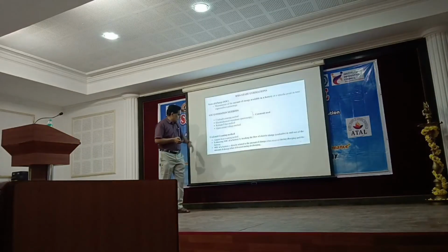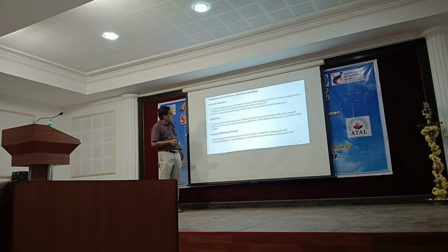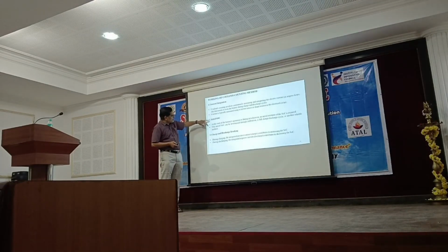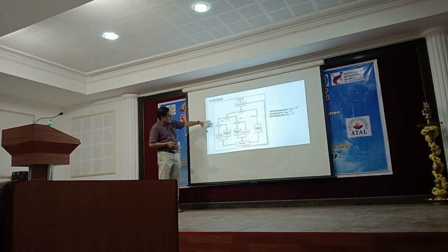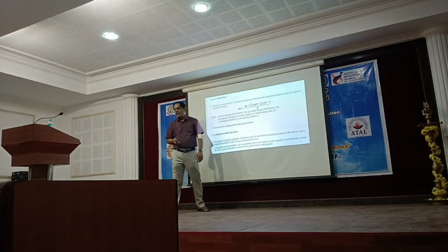And again, we have optional voltage measurement also. Coulomb counting technique is also a routine procedure. We estimate the current as a function of time. We call it ampere hour. I just directly go to current integration. You should know the initial SOC. And this is a typical flowchart to show you how SOC is estimated through Coulomb counting. You can see here the SOC formula.